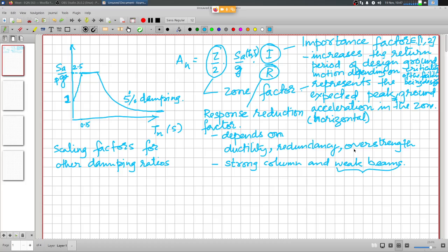you need to be careful, because it's your professional reputation at stake. So be careful when you use reinforcing steel, what is the grade of steel that you are putting in there, and whether it corresponds to the grade of steel that was assumed in design calculations.